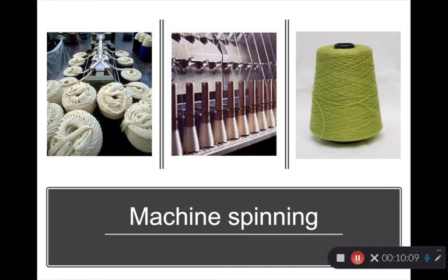But it's a drawing process in that you take the fibers and you continue to pull them along their length, but twist them at the same time. There's often a step between a sliver here on the left and a yarn called a roving, and that's where you have started to insert twist and made the yarn much, much thinner by pulling on it.